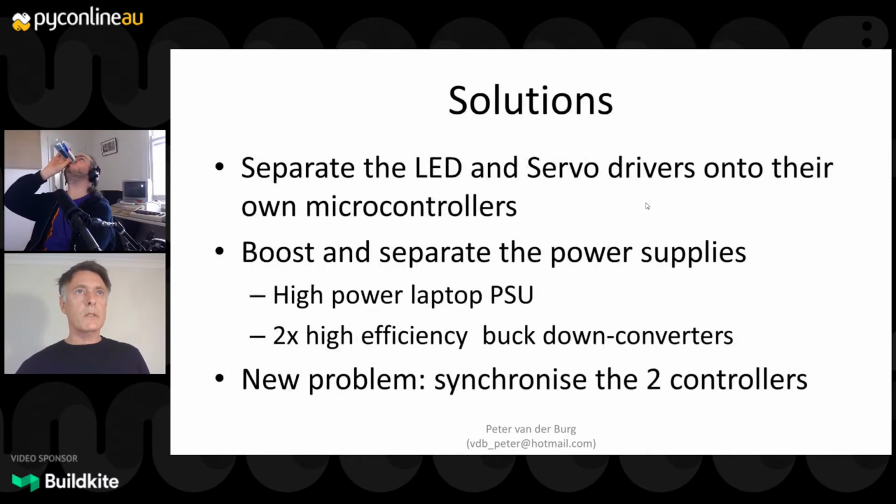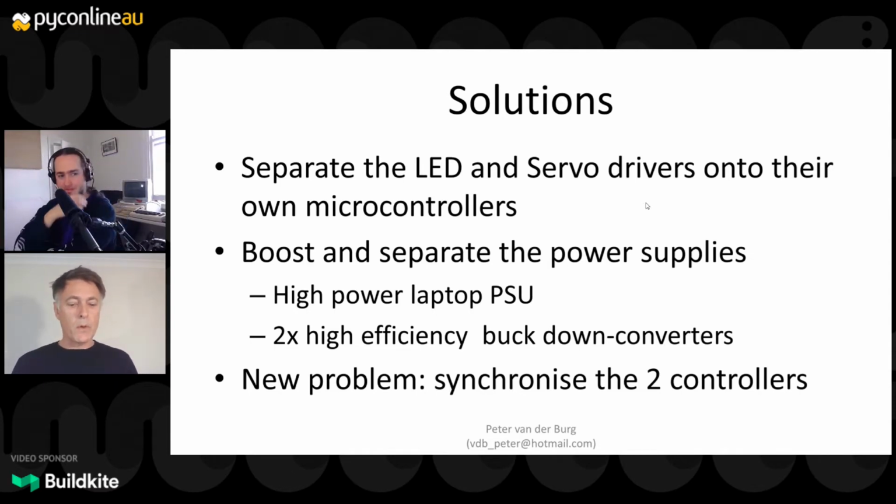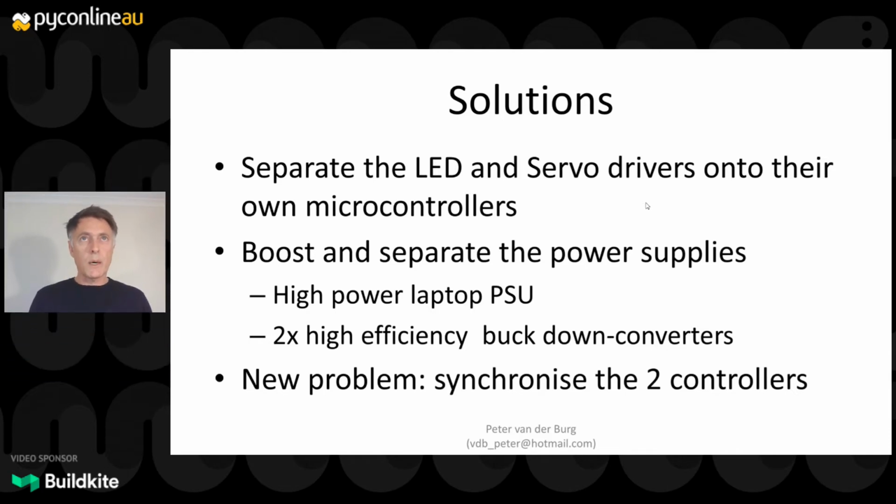So the first set of solutions was to separate the LED functions from the servo. So the electronics, we're talking about the hardware. So the LEDs were connected to one microcontroller, while the servo was connected to another. And I also boosted the power.